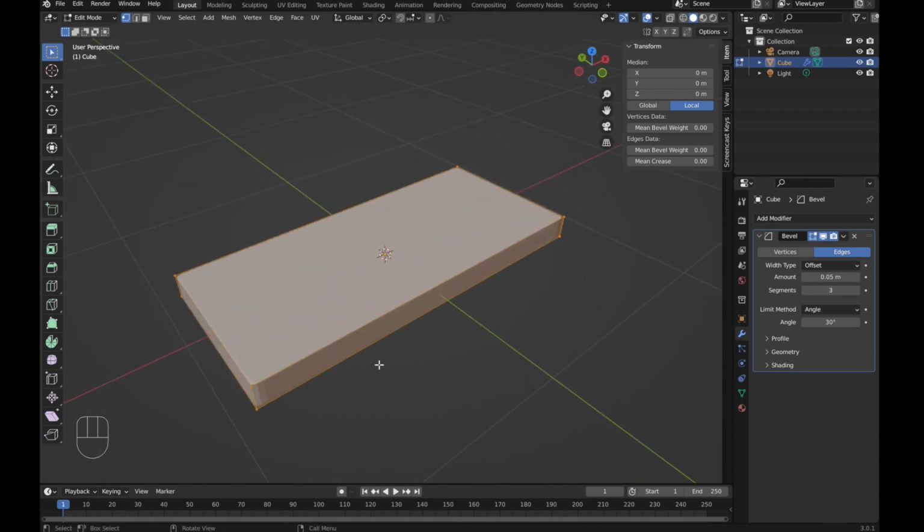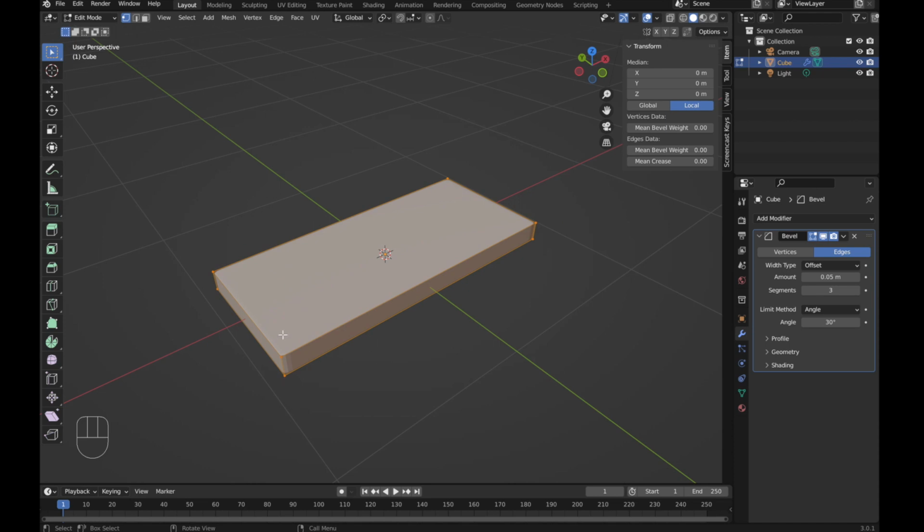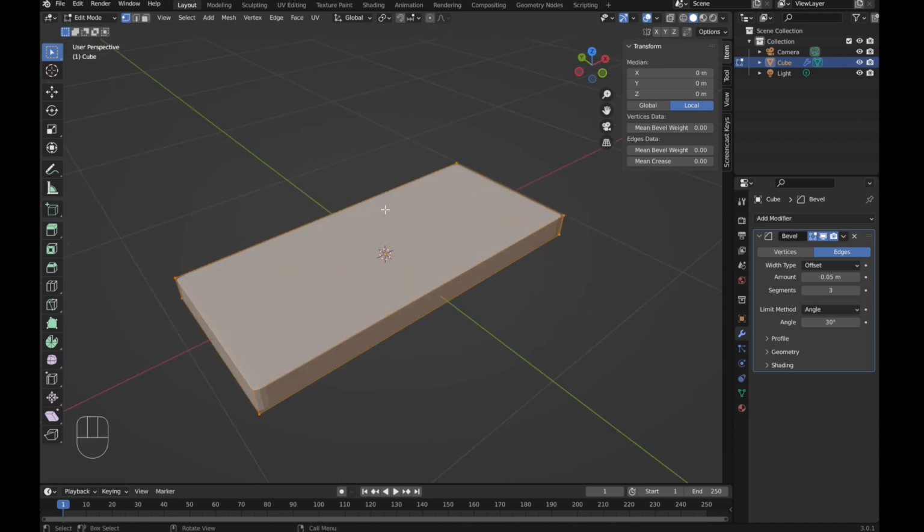Next, create the side and backrest risers. To make them, perform a loop cut along the sides and back and raise the cut plane. If you press Ctrl+R and move the mouse, a yellow section line will appear, so move the mouse and left-click to confirm.